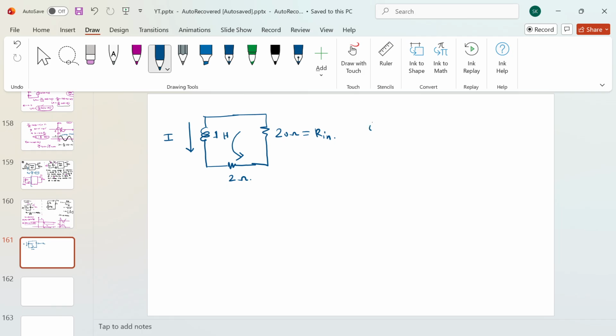Okay, so the current expression for an RL circuit is simply, maybe I can write the entire expression: I infinity plus [I of pi by 3 minus I of infinity] e to the power minus (t minus pi by 3) by tau.